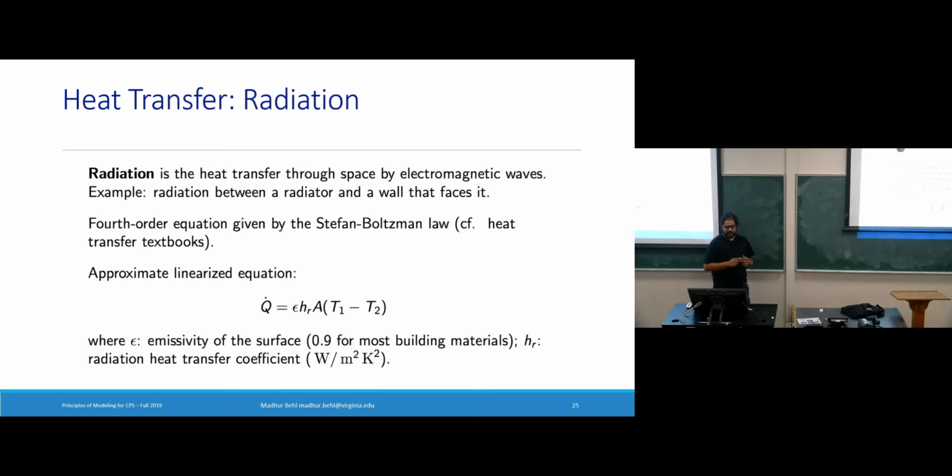And then the final piece is what you call radiation. This is perhaps the most complicated one, but I'll again throw out these keywords to trigger those neurons that you have seen before. There's something called black body radiation. So any surface which is above 0 degrees Kelvin is emitting electromagnetic radiation because of its temperature. In fact, if you recall, it's proportional to some temperature to the power 4, which is why hot bodies emit a lot of this electromagnetic radiation.